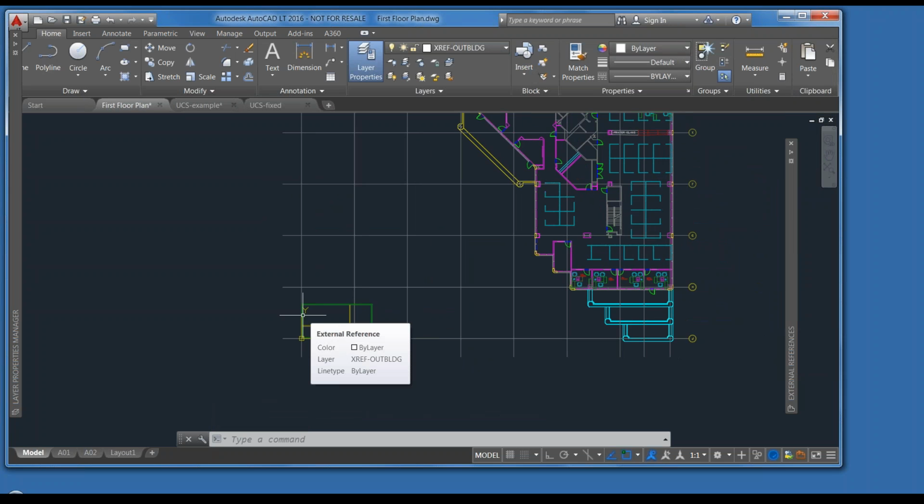And just a note about Revit, Revit can be introduced in a workflow like this even with 2D drawings only, because Revit can export as a DWG. So perhaps you're working with another office or engineers that are on Revit, you're on AutoCAD. Just make sure that they are using a similar origin point or a project base point that matches your insertion point here. Then in Revit, they go to their layout and export it as a DWG.